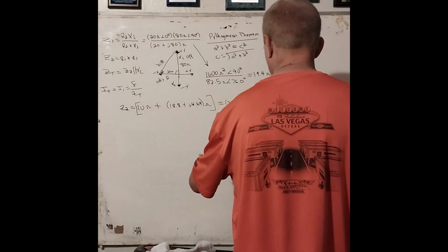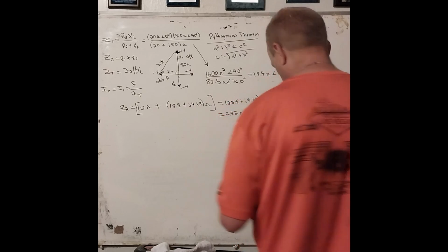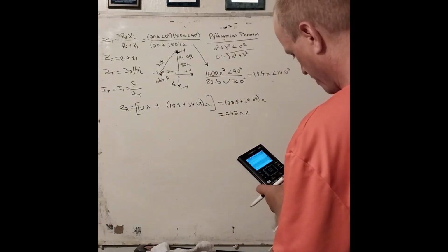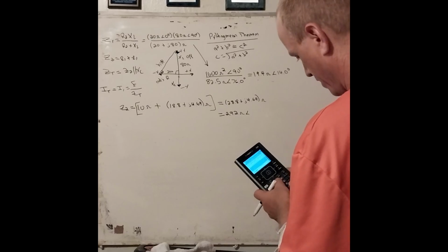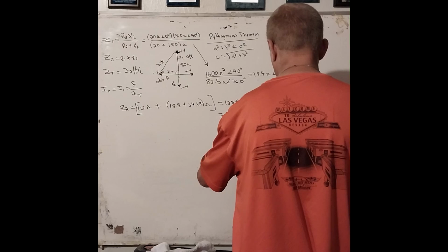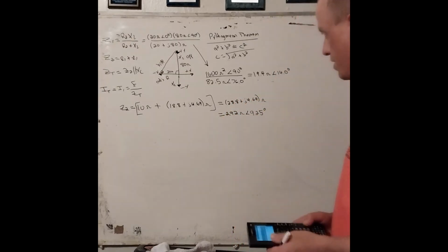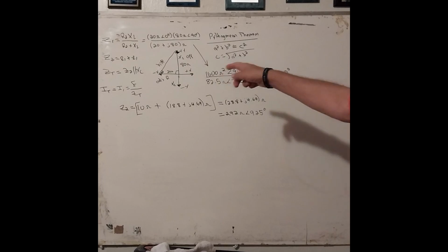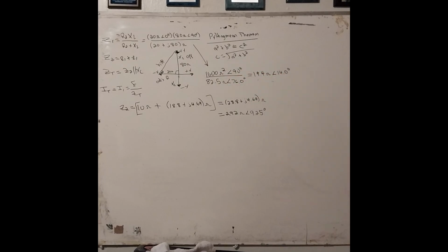This is equal to 29.2 ohms at an angle of, I'm going to take the inverse tangent of 4.69 divided by 28.8, we get 9.25 degrees. So that's Z sub 2. And we know that Z sub T is Z sub 2 parallel with XC.